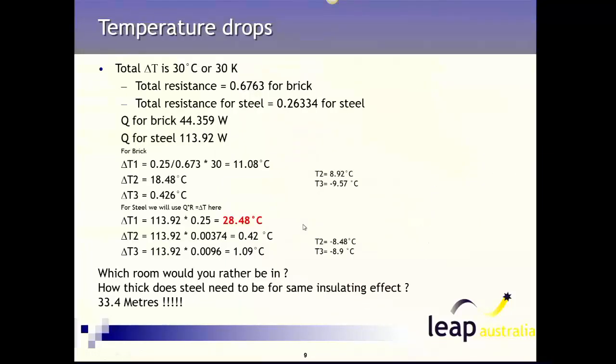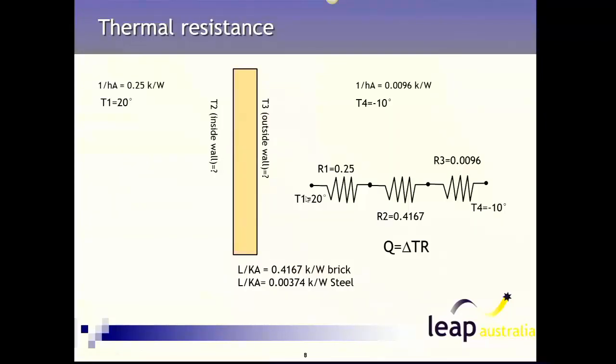So if we do some quick hand calculations, the most important thing is that the heat flow will depend on the total thermal resistance. Because these two temperatures are fixed, there'll be a certain heat flow across that entire thermal resistance network that will change based off that total. The only variable here is this R2, and the relative temperature drop across those three resistances is on the same scale as the resistances themselves.